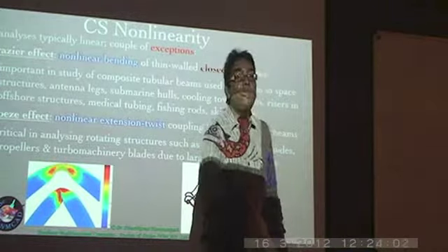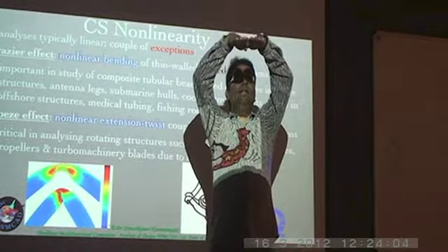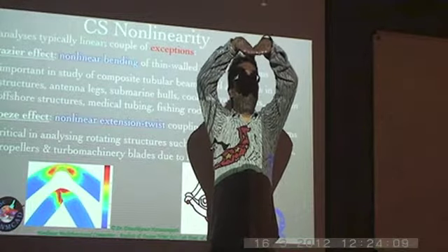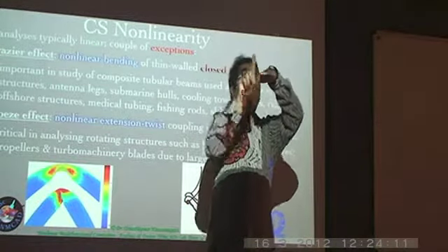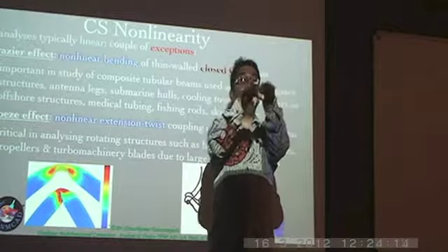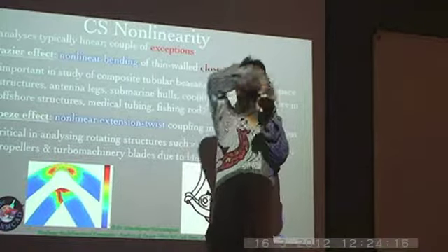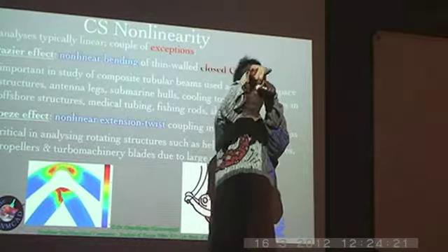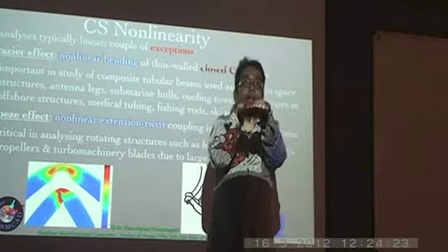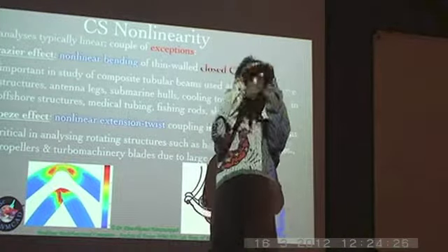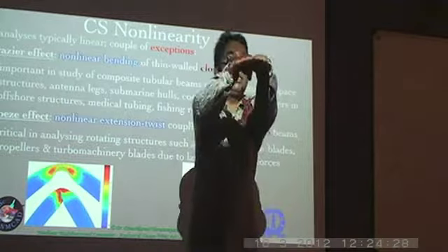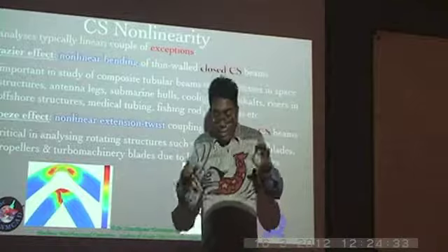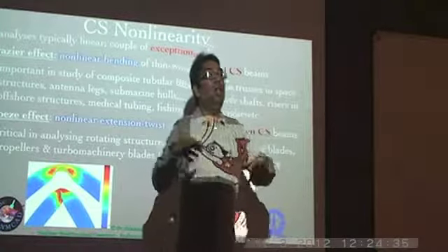On the other hand, moving forward changes the rotor plane from being horizontal to tilting forward, so that the resultant force coming from the lift acting on the blades, which is always perpendicular to this rotor plane, instead of being vertical, now has a component which is horizontal as well. Therefore, in addition to balancing the weight of the helicopter, it also starts moving forward because of the forward component of the force. But this is as far as what actually happens to the helicopter.